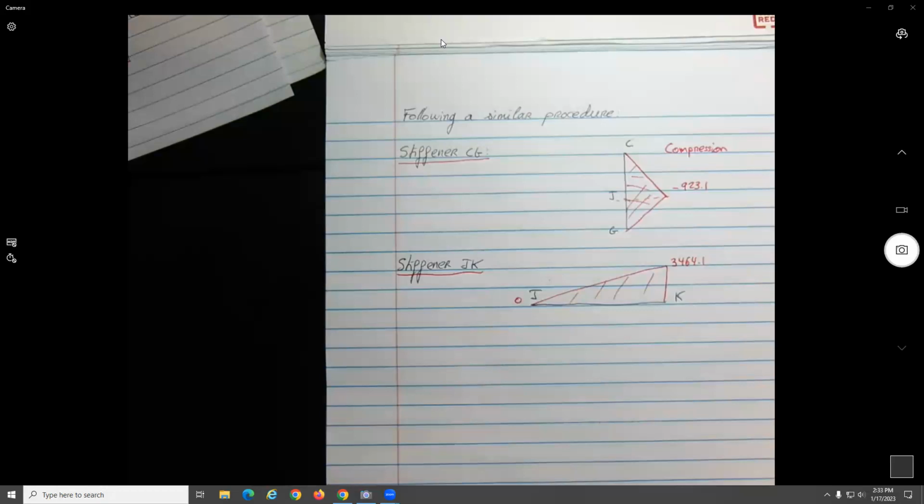So knowing this, we can now take the moments about point O and equate this to 0. Positive counterclockwise. So this will give what? M12, which is the moment over here. Now, the shear flow Q12 creates a clockwise moment, so it will be negative. Remember, this is force times what?